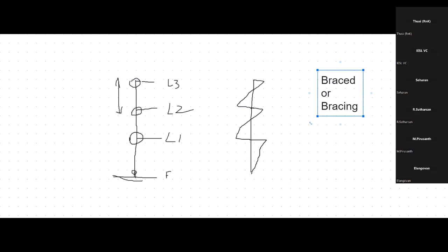That means the core walls are going to provide lateral restraint to this column. In a nutshell, this column is laterally restrained, so I can represent it like this. This column is braced laterally at each level. This spring is represented by the diaphragm. So our floor diaphragm is going to give the support for this column.